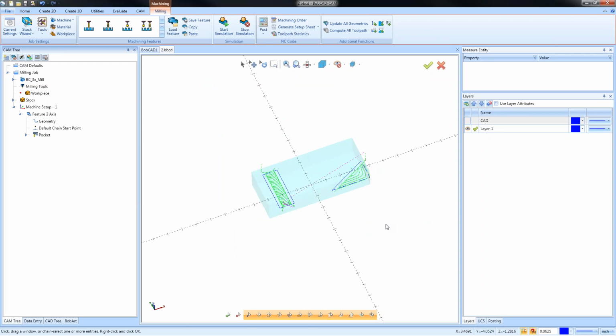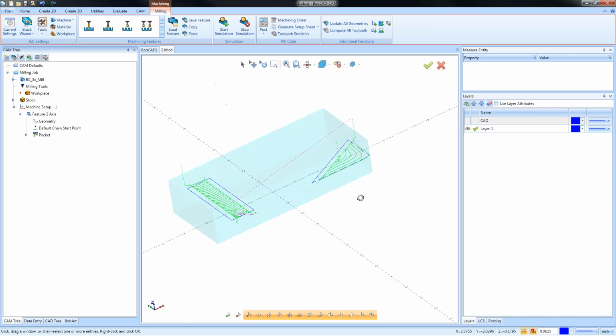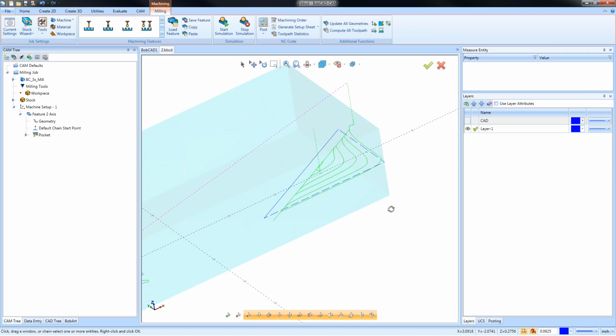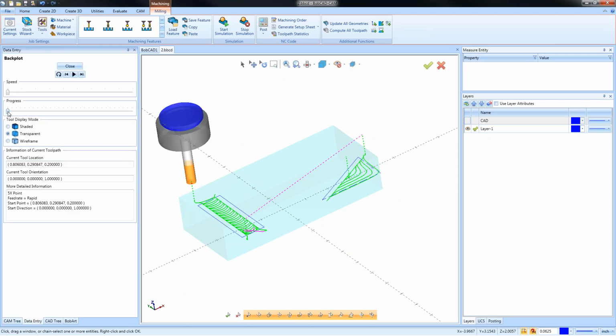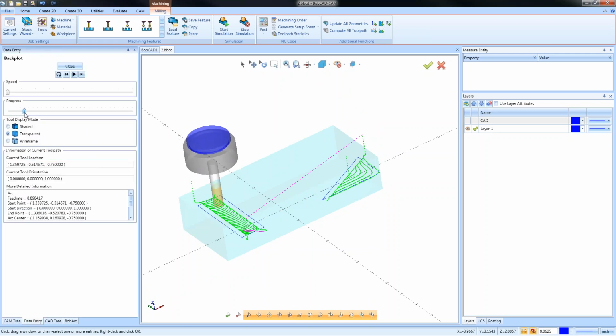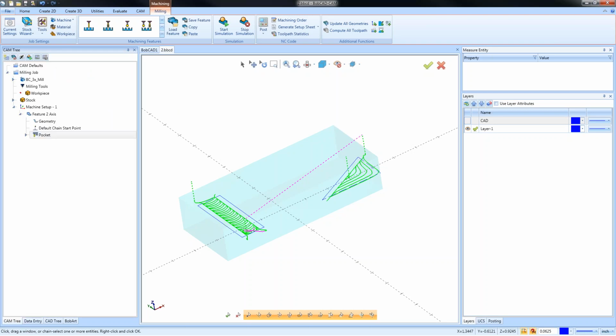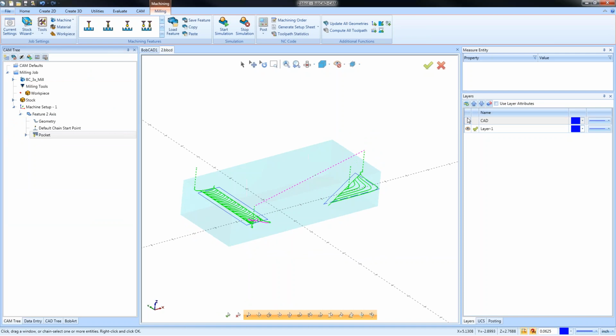This is where it does more side roughing, the loopy tool paths that you're used to seeing. That's what our adaptive routine is. There's a lot of benefits to this style of cutting strategy, but of course it's going to depend on the material you're working with, and also your equipment as well. So that's a little bit about two-sided open pocketing.